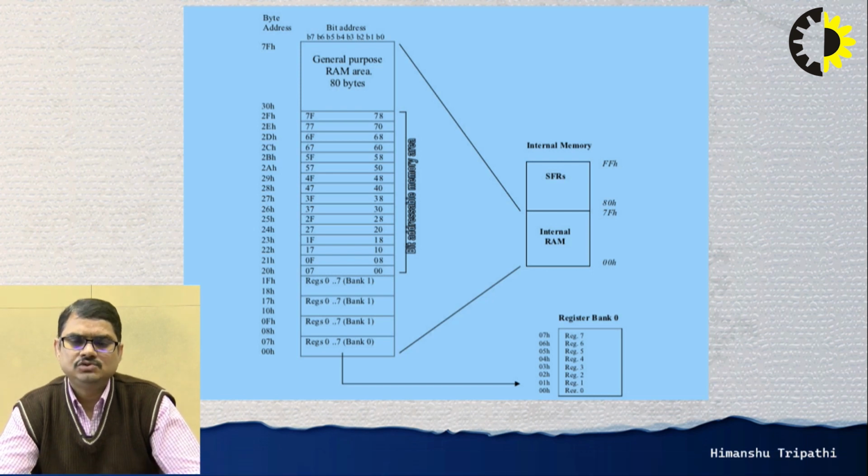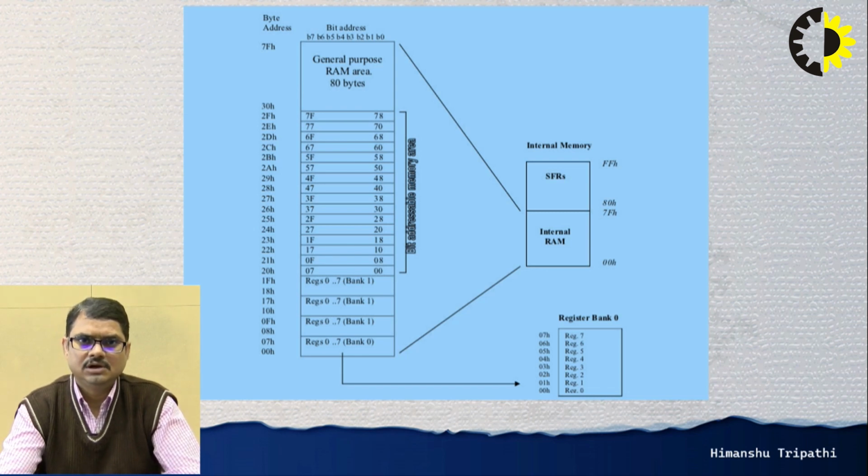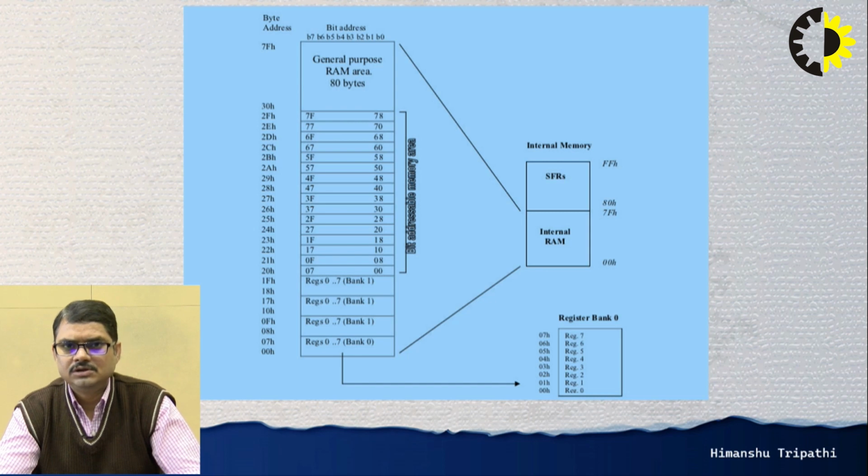There is no need to engage an 8-bit memory location for that particular output. So here we can use 1 bit of memory inside this bit addressable area, and we can save a good amount of RAM in our application if we follow these principles.